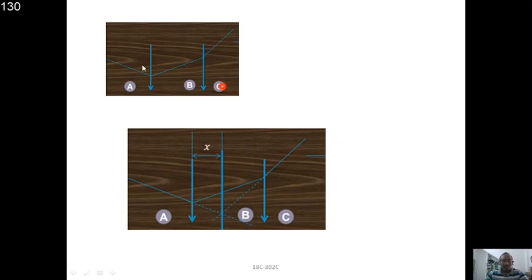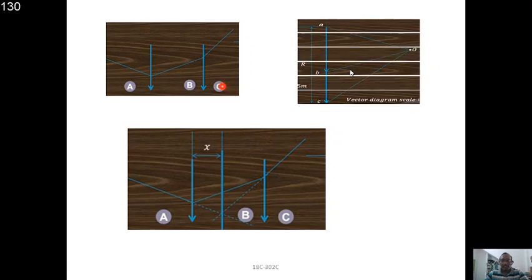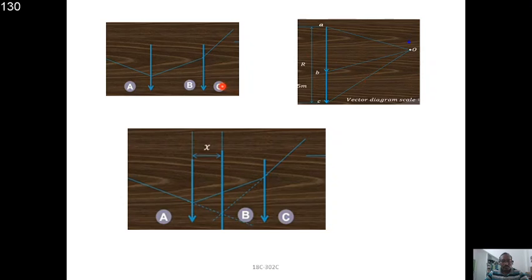So this is A1, this is A2, similarly A3, A4, A5, A6, like that all the lines you have to draw. After drawing these lines, take some pole O, a reference point, and this AB is equal to area A1 only, and BC is equal to area A2. So you have to draw a continuous area polygon by combining these at the pole point.